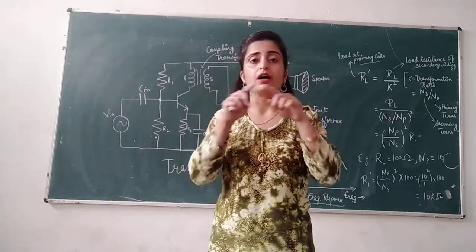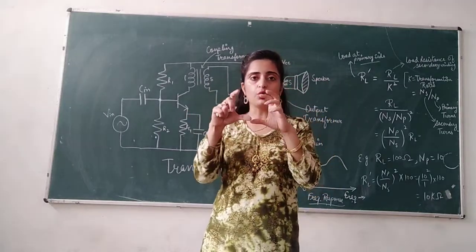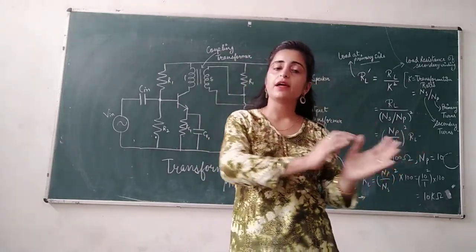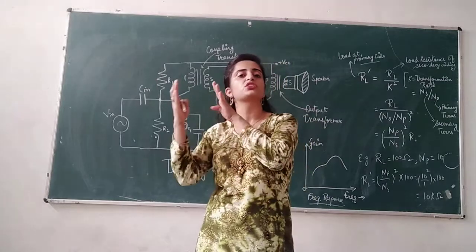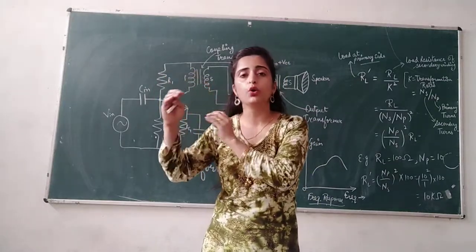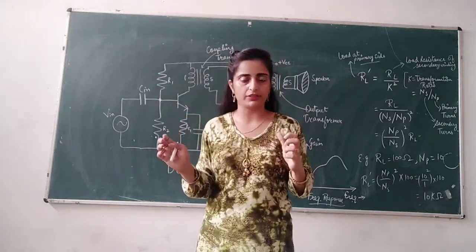So a circuit in between should be used so that its input impedance matches with the circuit and its output impedance matches with the external output device that is connected as a load, that may be a speaker or anything else that you have connected over there.